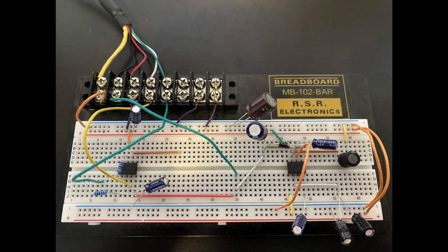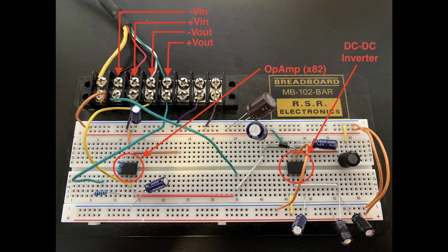First, the load cell circuit. There's a positive and negative excitation voltage applied to the Wheatstone bridge. The positive excitation voltage is sourced from the power subsystem and the negative from my DC to DC voltage inverter. The output signal of the load cell passes through an amplification circuit. This DC voltage is then sent to the ADC pin of the patient room STM32. This is the primary way that the fluid levels in the IV bag are measured.